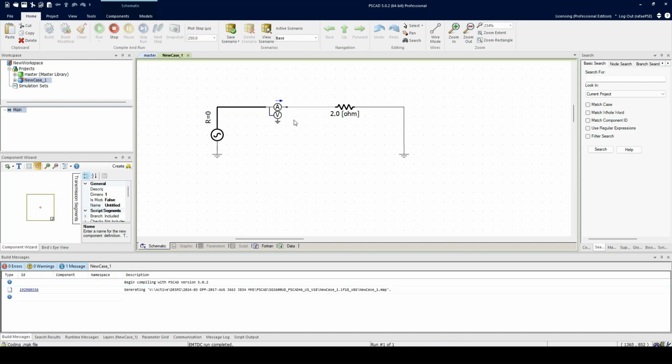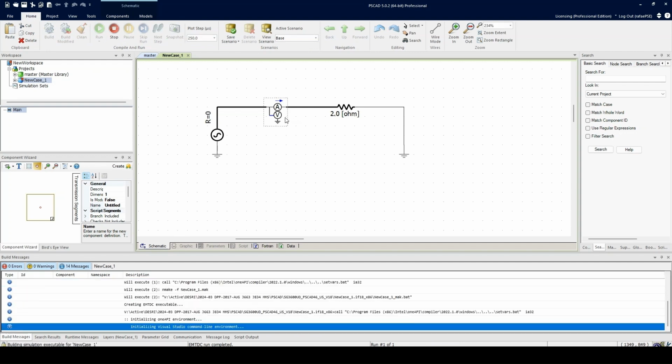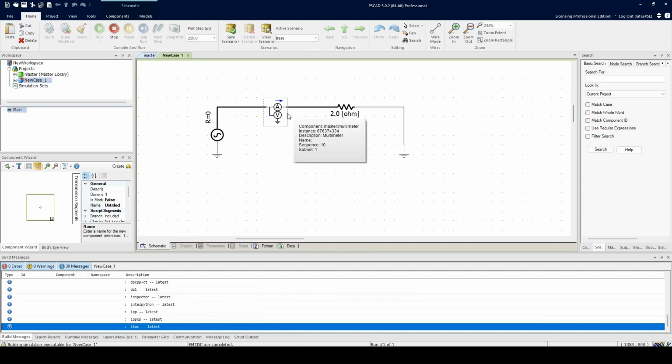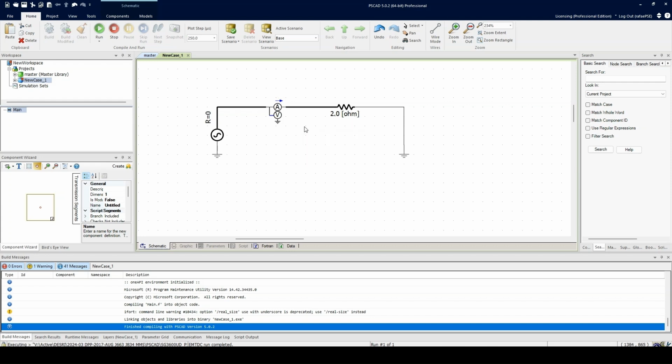But as I'll show you what I mean, I have now created the signals, but I still haven't set up the way for us to be able to see that data. So now the simulation will be recording the data. It will be recording that into the signal names that we provided, but we just haven't seen those signals just yet, right? So you could see now it's running, it's annotating, it's showing that the voltage at this point with respect to the ground is 30 kV. This is the power and the Q that you're seeing, but what we're not seeing here is the waveforms.